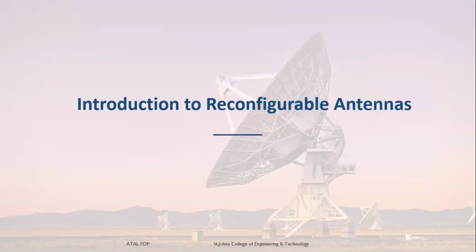Anyone can respond, those who are online. Can you tell me what are the important parameters of an antenna? Once I design, what do you look for? Radiation pattern, sir. Yes, radiation pattern. Return loss, sir. Return loss is nothing but S11 characteristics. Yes, frequency of operation. Beam width. Beam width is obtained from the radiation pattern. Correct. One more important thing you forgot: polarization. Yes, sir.